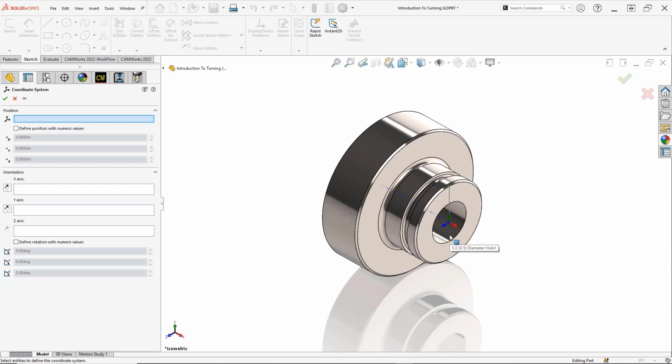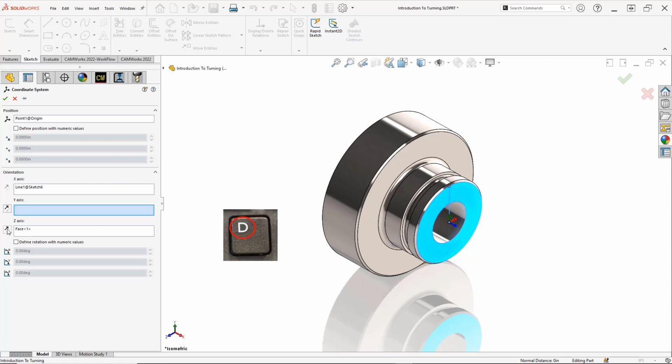Axis colors, green, red, and blue, help determine proper orientation, and it is the same colors used for the SOLIDWORKS reference triad. Toggle the reverse direction icons to achieve the desired result as shown in the SOLIDWORKS display area. Once done, press the D key on the keyboard or the green check mark, as this will display the Property Manager confirmation dialog wherever your mouse is currently at.